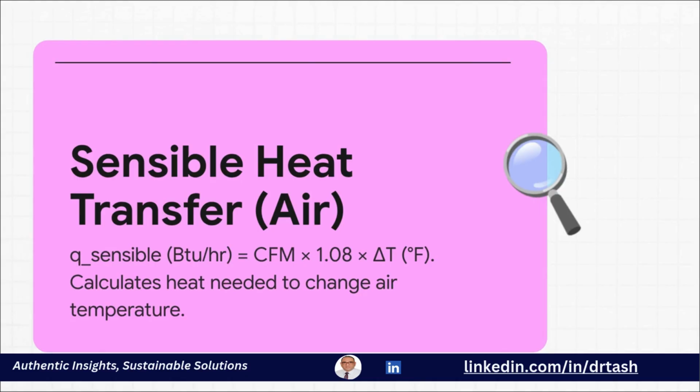And that constant, 1.08, we all use it every day, but it's good to remember where it comes from. It's just a neat package of standard air's density and specific heat times 60 minutes. It just makes calculating the energy to change air temp so much easier.